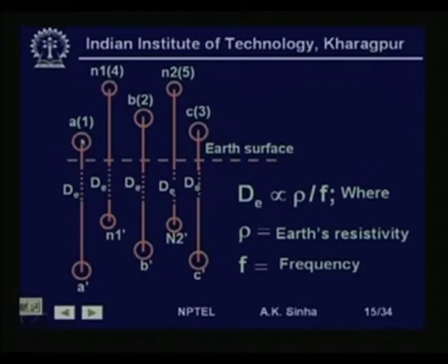That is, here we have 3 phase conductors A, B and C, and we have 2 earth conductors or ground conductors, which are N1 and N2. Now, what he proposed is, for such a system, the ground current flowing can be represented by a conductor A dash, which is directly below A in the ground, at a distance dE from that conductor.